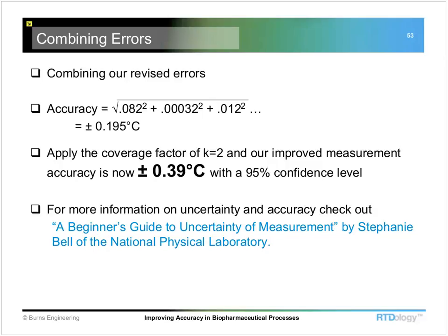By looking at their installation, they determined that someone had actually strapped the probe to another device within the incubator, and that device would heat up a little bit as it was running, and the sensor was detecting that temperature. So the fix was very simple, just to mount the sensor in a different location within that particular incubator.